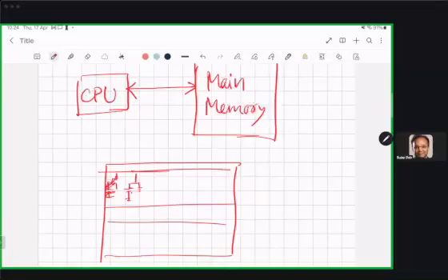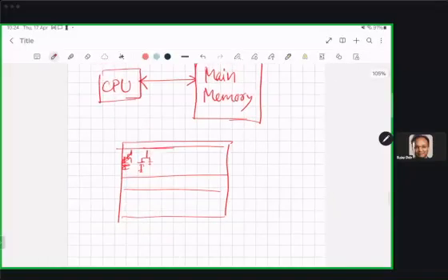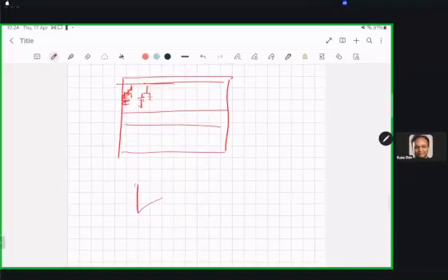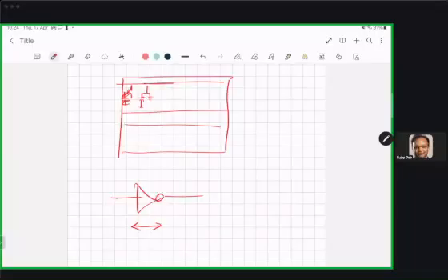Now in digital circuits, or for that matter, any circuit, let's say I give you an inverter and ask you to find out what is the delay of this inverter. So how do we calculate delay? We say that, okay, if input changes at this particular time, at what moment the output changes. So after certain delay, the output will change. So you measure the delay, right?